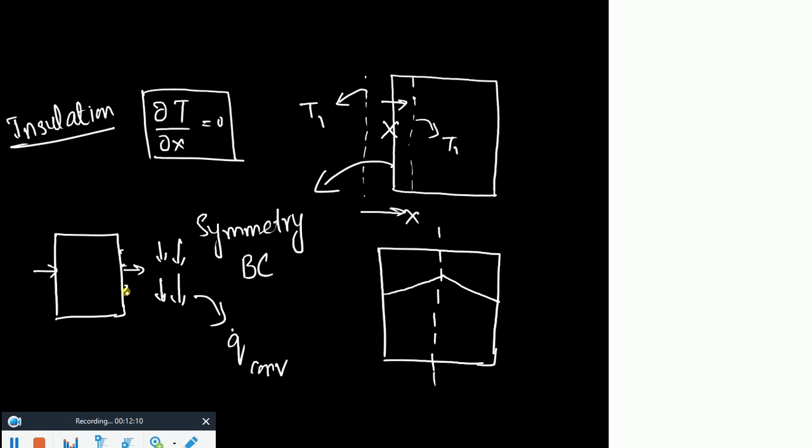One is storage and the other one is generation. So you can't store it, you can't generate it. So if you look at this surface, whatever is coming in from this side has to go out from this side. Now from this side energy is being conducted, and on the other side energy is being convected. So these two need to be equal.